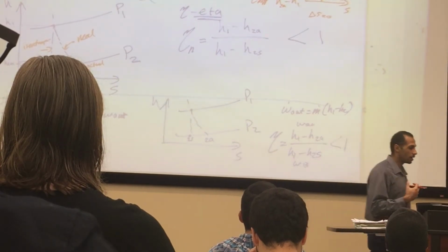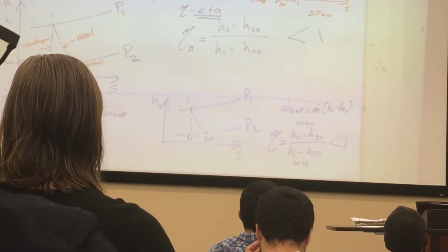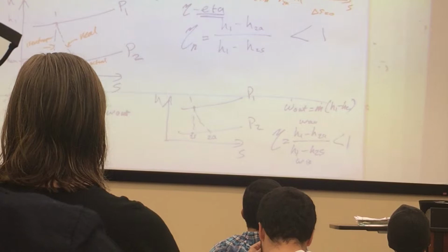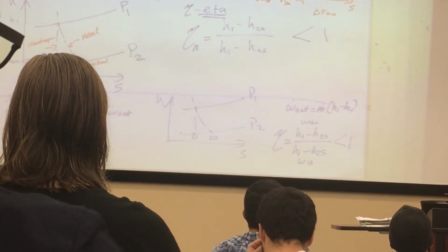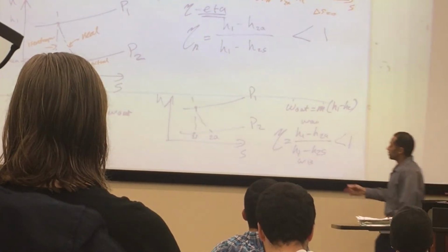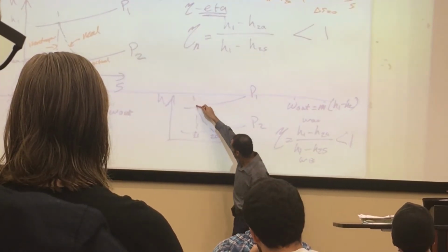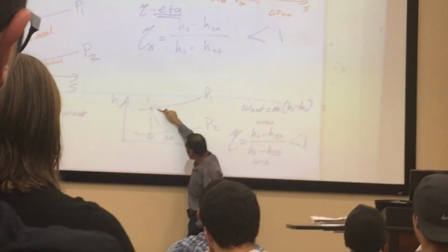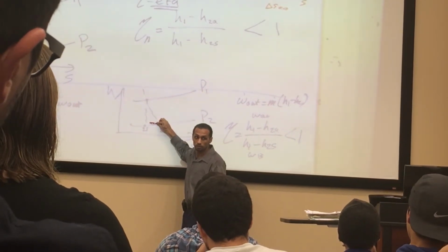It's not a clean-cut flow path that you have in there. You have losses, think of it as a drag force. You have significant drag forces that are happening inside of the turbine blades that reduce the overall 100% efficiency. So therefore, you end up with a non-ideal expansion. Ideally, I could get this much work, but I don't get this much work. I get only up to here. Does that make sense for the actual?